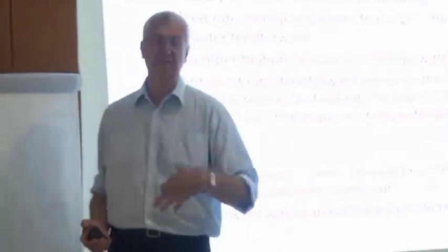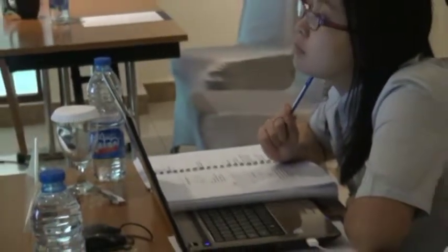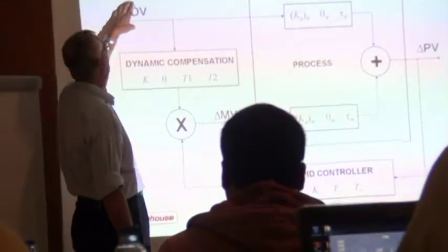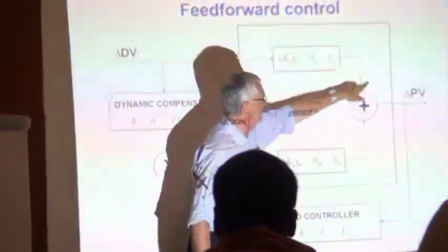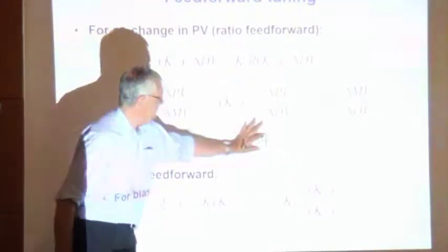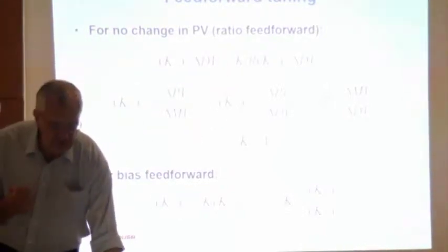Why? Because you either have a flow controller on the distillate or, in the less preferred version of the material balance, on the bottoms. What do we want this value to be? 0. Okay, so if there's a disturbance to the feed rate, we multiply by process gain and it comes in here. So nothing happens. It's always like that, why? Because I have replaced KPD with the definition of KPD, not a numerical number or a value. This is based on definitions. This applies to any process. Okay? So the fact that it changes sign isn't a problem.